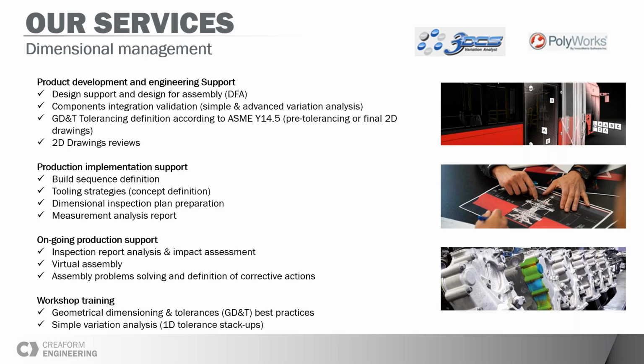There are a lot of possibilities, and it shows you the worst case and the envelope of how it could look. So how your gap could look if your hinge is not within a certain specification or is at the end of a certain tolerance. Well, the impact it has when it closes, so it's not flush anymore, or the gap goes taper. We can analyze all that and find out which is the greatest contributor to that functional failure. So tools exist, we master them, and we have experts. Just keep that in mind.